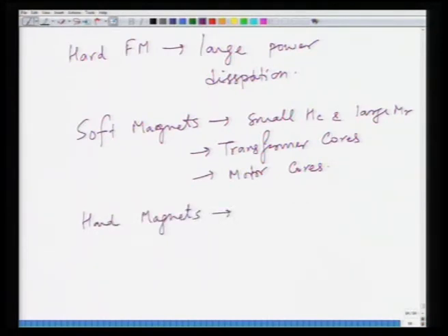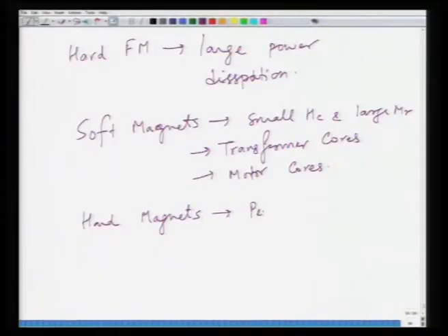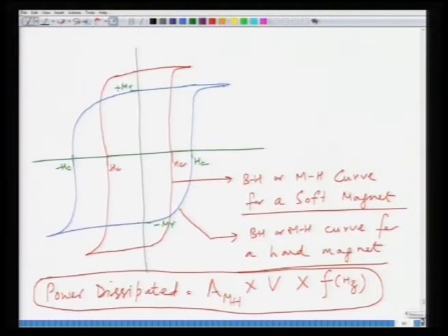find application in those areas where you want the magnetization to be reversed with difficulty, where the domain reversal has to be difficult. So, they find applications in permanent magnets and memories, because you do not want your data to be lost. You want to retain that particular state. I didn't introduce this, but just like a ferromagnetic material, these states which are plus Mr and minus Mr can also be used as 0 and 1 states of memory in a binary memory data storage.